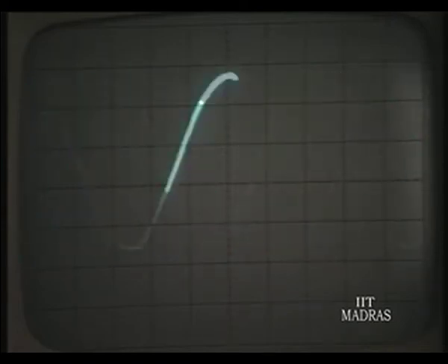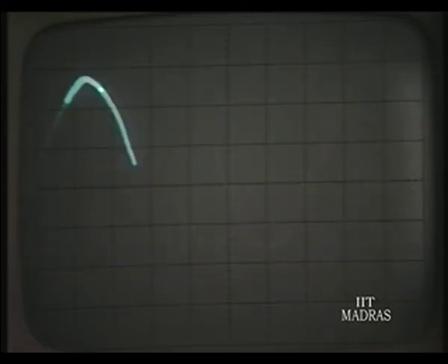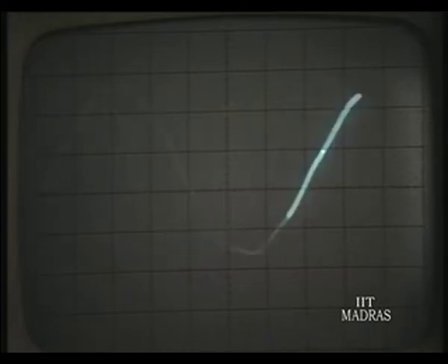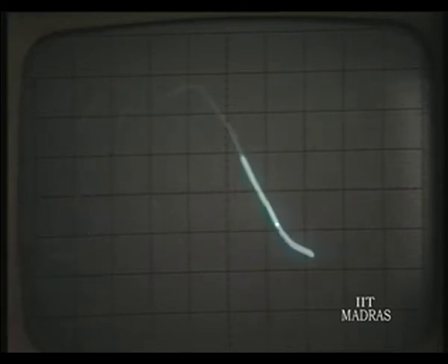Okay. So, this is as far as deviation is concerned. And the deviation produced at the output should be the same as that at the input. If it is a low frequency modulating signal, the deviation produced at the output is going to be the same as the deviation produced at the input. Now, she will change the frequency of the modulating signal. It is reduced, you can see the frequency is reduced, very low. Increase, the frequency of the modulating signal is increased, and this is the FM detected output.